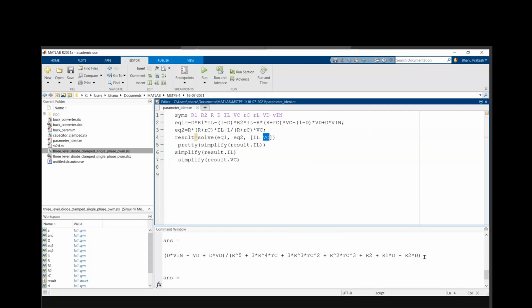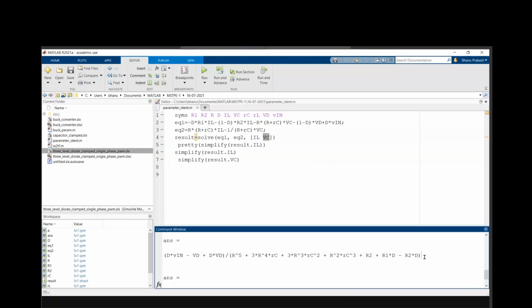It is not just for the buck converter. For any converter that you take, with its equivalent representation, and you want to find the values across the respective passive element components, whatever state variable components you have, you can find it not as a function of time but as a function of duty cycle. This will give you a specific value of inductor current for a given duty cycle. So this is what we want.